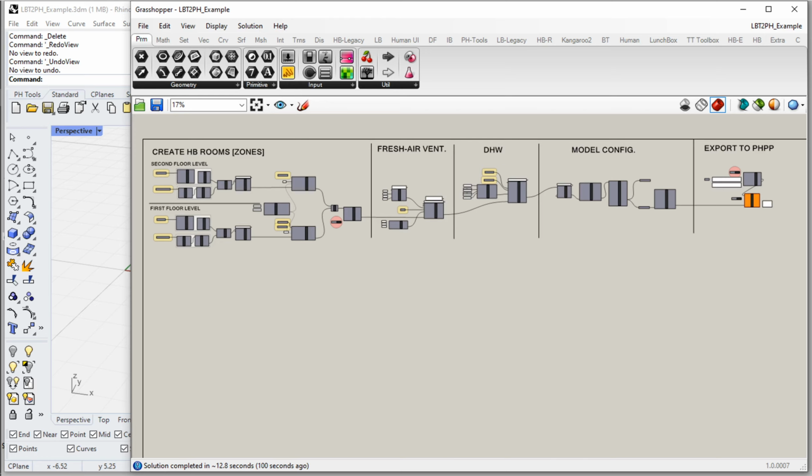We've configured the PHPP with the number of occupants and the types of certifications that we're after in our last video. And our last piece of the puzzle here, our last main piece, in order to get a full set of results, is to build out the heating and the cooling systems for the building.